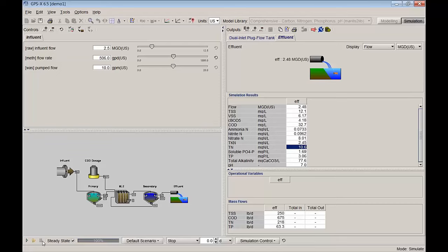If we push that up again, now we can see that it will reflect that new carbon dosage that is no longer being carbon limited in the anoxic zone like it was previously. We can get a little bit better performance, and we can see now we can get down from 11.9 down to 8 with dosing a bit of methanol. And of course, this is still a regular soluble substrate, and it is still affecting all of the other things that are going on in this particular system. We have a specific biomass type here, methylotrophic biomass, that is doing its job, but that soluble substrate is available to other biomass types too, and it also could theoretically make its way out of the effluent.